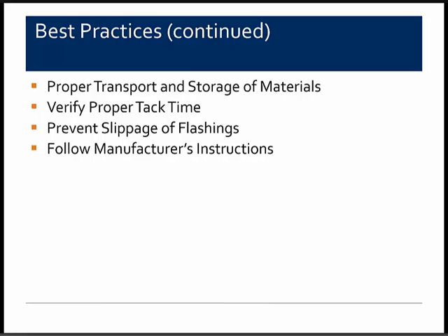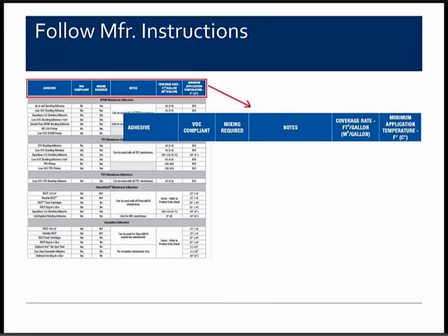Again, when you're installing the adhesives, you want to make sure that the two mating surfaces are held together long enough so that the adhesive can cure and do its job. And again, follow the manufacturer's instructions. This particular slide just shows that manufacturers have various charts, coverage rates, things of that nature to give the contractor a couple of tools to follow during the installation of the materials.